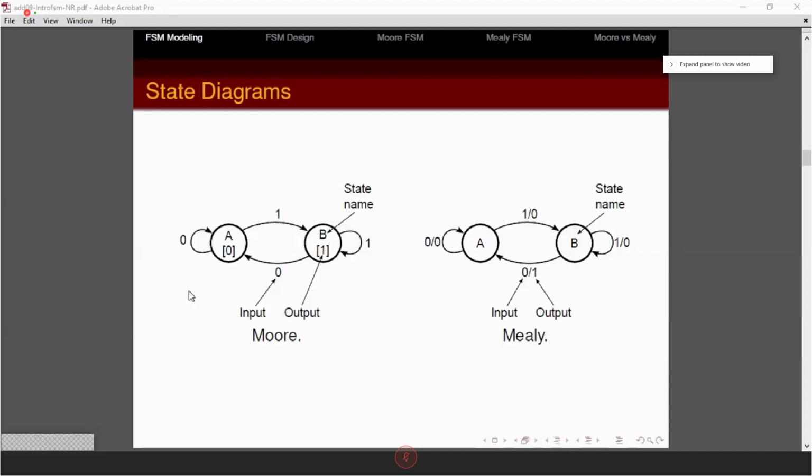Depending on how many states, for example here only 2 states, if you use a binary system to name these states, 1 bit is enough, because you can say state A equals 0 and B equals 1, and it doesn't overlap. This is where we say n is equal to 1, so 2 to the power of 1 is 2.